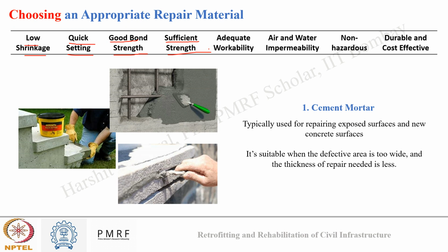And here is where you can understand how repair is different from retrofitting. In repair, we are not increasing the strength of the structure, we are maintaining the strength of the structure while improving the durability performance of the structure. How? By repairing the defects in the structure.